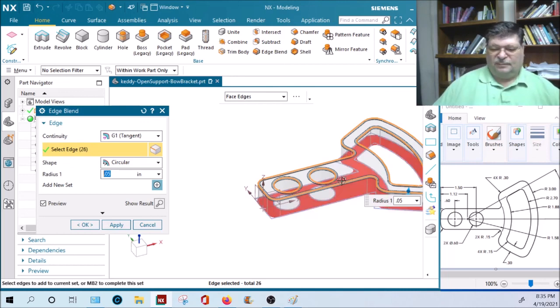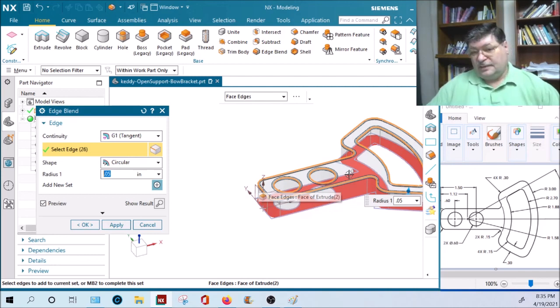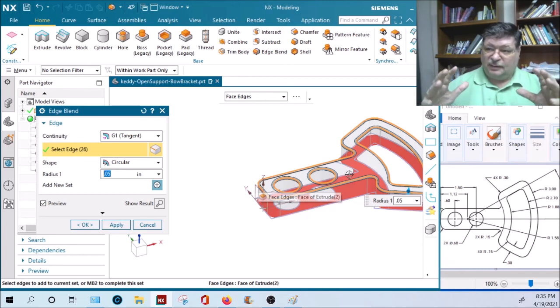And sometimes that'll basically round things off. That's what they do to dice. You get a 6-sided die. Typically they are cubical, and then they put them in a media of hard pellets or other media, and they vibrate it, and by random chance everything gets vibrated the same, so the corners slowly get ground down. The longer you leave it in there, the rounder the edges get.